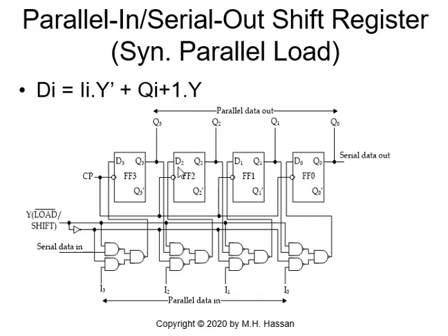So Y equal to 1 will be a shift register, allowing you to shift the data from the left to the right. The same thing for D1. If it's D1, I will take Q2. D1 will have a Q2 when Y is 1. However, when Y is 0, we will load the data I2 to D2 and I1 to D1.